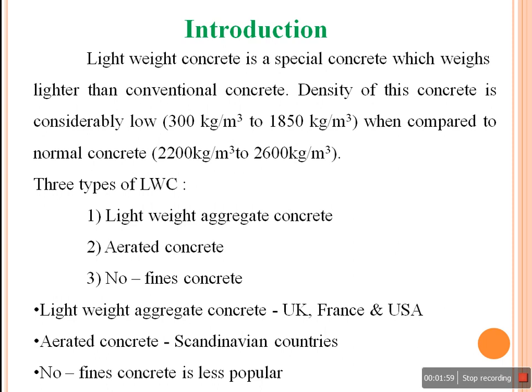So what is lightweight aggregate concrete? When we use aggregates that are light in weight, that is lightweight aggregates, to manufacture concrete, we call it lightweight aggregate concrete. So what exactly is aerated concrete then? If we are introducing gas or air bubbles in the mortar, this is called aerated concrete. Then no fines concrete.